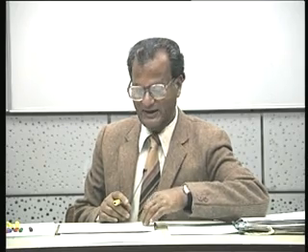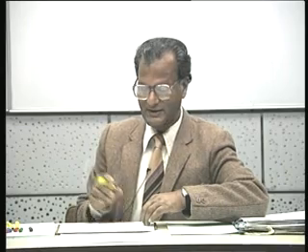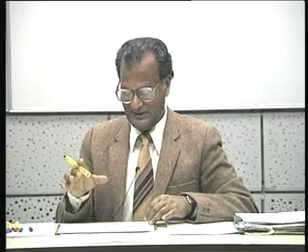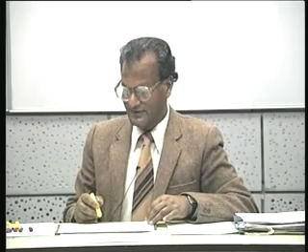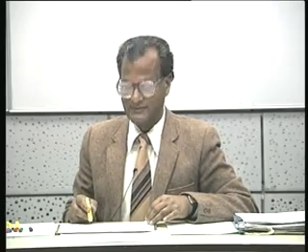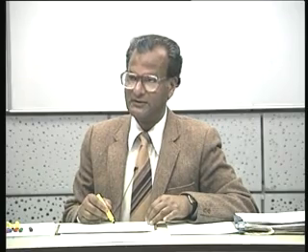No, I am trying to show you an example of a two-port which is neither reciprocal nor passive, and it is a circuit which can be made with transistors or op amps. I am not synthesizing what is inside the NIC. Inside the NIC you will look at in a different course. What I am showing is that the NIC is an example of a two-port which is neither reciprocal nor passive. It is not reciprocal is obvious because H12 is not equal to H21.